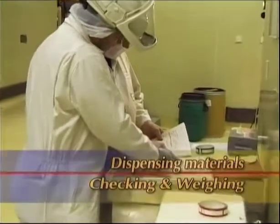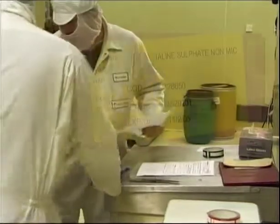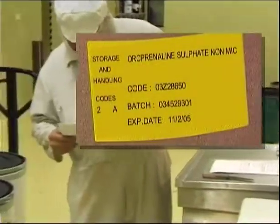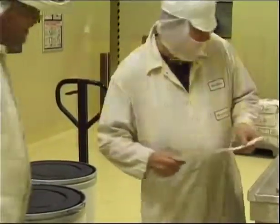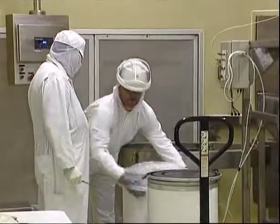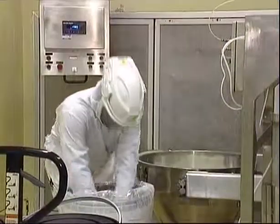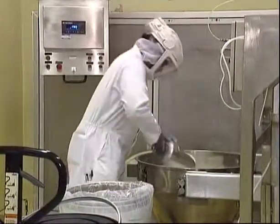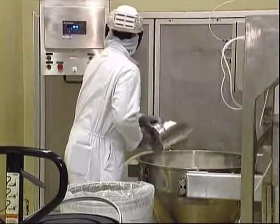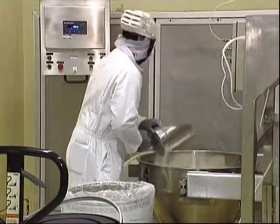When it comes to the actual dispensing, the first thing is to check that you are using the correct material, that the batch number is correct, and that it's not past its shelf life date. Obviously, you'll check that the bulk container from which you are taking the material is not damaged, and equally that the container into which you are dispensing is in a clean and fit state. The actual weighing and dispensing should be done with the minimum of movement to limit dust, and when done, close and label the container as detailed in the SOP.